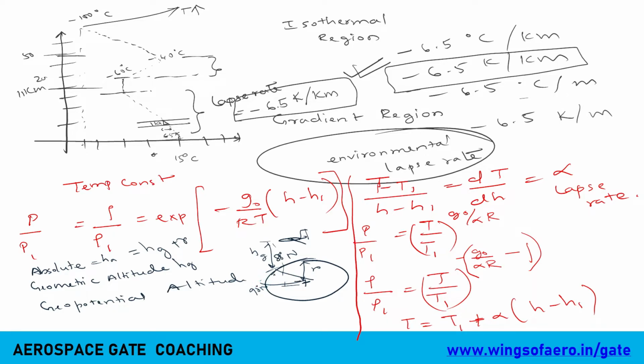So there will be variations in the latitude. With the variation in latitude, how can we measure the height of the object flying? That is defined by the geopotential altitude. So there is a formula, defined as h, which is found by r upon (r plus hg) into hg. Fine, clear?